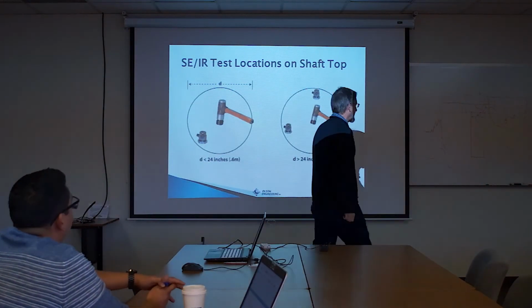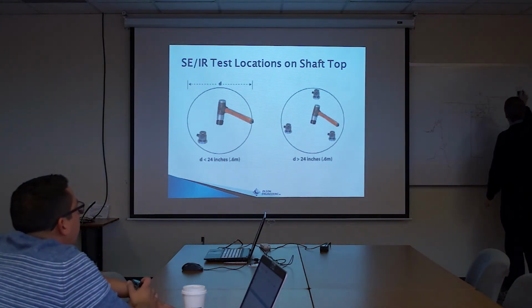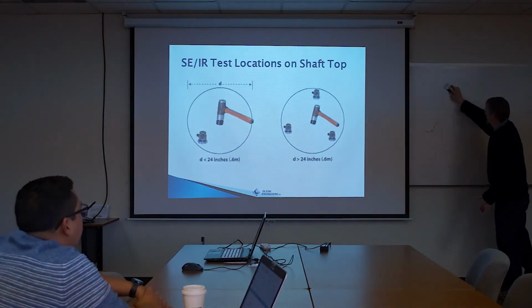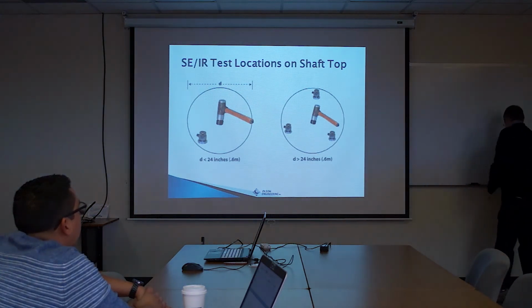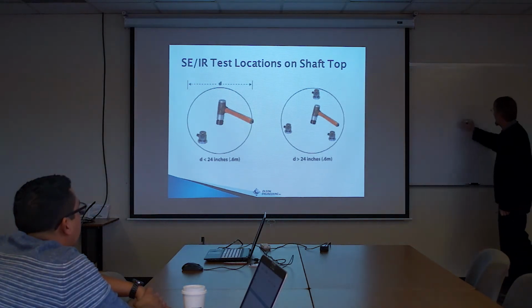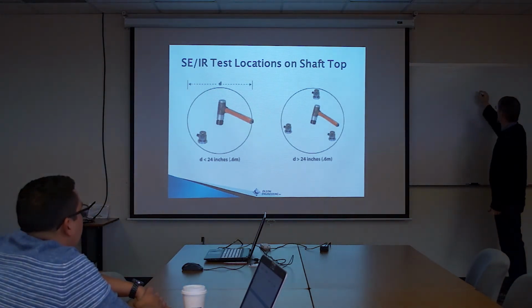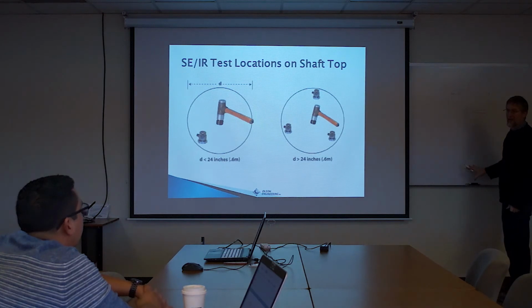And the reason they do that is you can think of a worst case shaft situation, where you have a large diameter, like a 6-foot diameter shaft. If you mounted your accelerometer here and you hit here and you have a partial defect here, your wave energy takes a little while to develop all the way across the shaft.